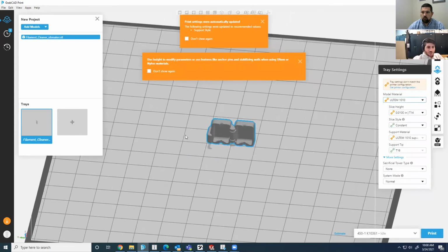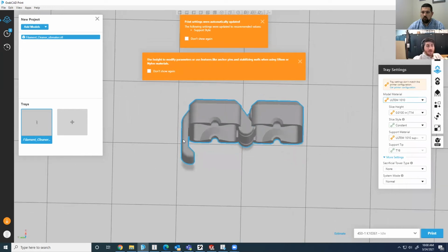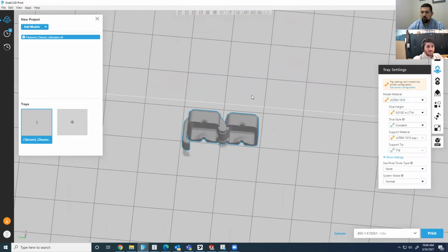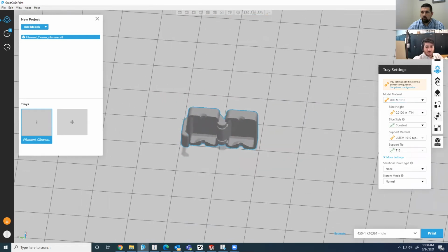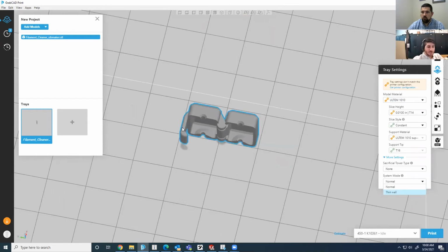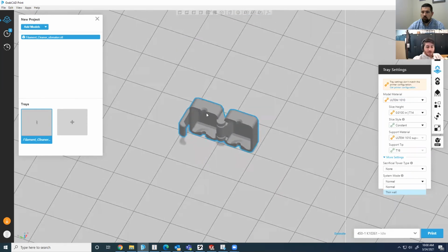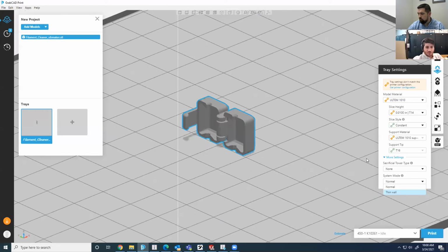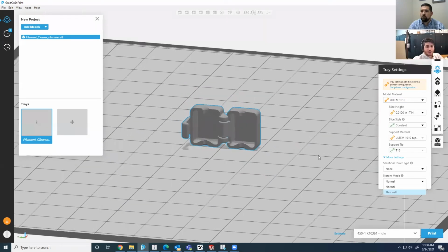If this wall was thinner than, I believe, 0.1 inches off the top of my head, then you would need to use this mode here, which is called thin wall mode. This reduces the oven temperature and will make sure that this part here doesn't become overheated, warp, or worse, melt. And that is something that applies to nylon material as well.